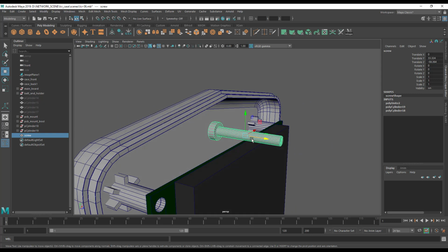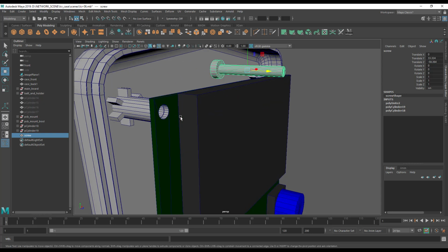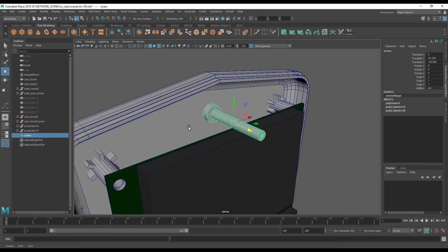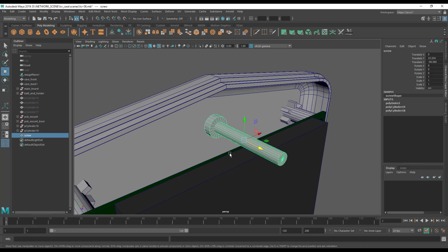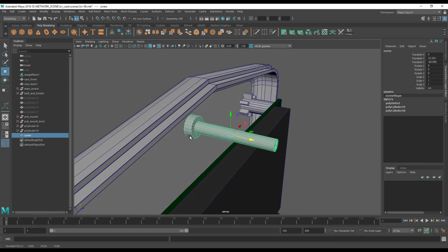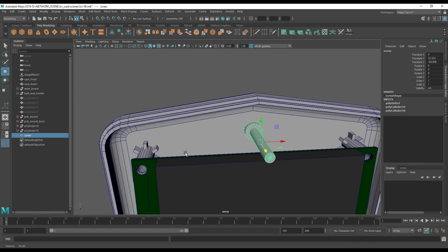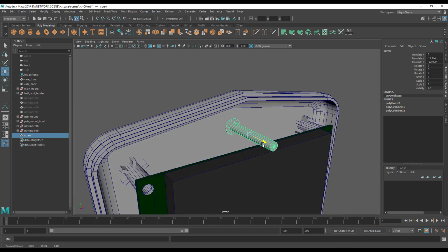Now our screw is an M3 screw, the same size we use to mount the mainboard, which means it's going to have a head circumference of around 5.5 millimeters or a diameter of 2.75 millimeters. So we need something wider than that on this side to receive it. We're also going to need to punch a 5mm hole through the case itself.